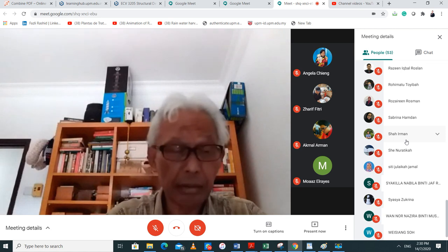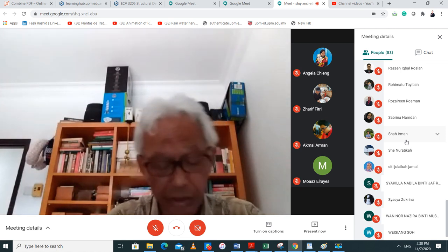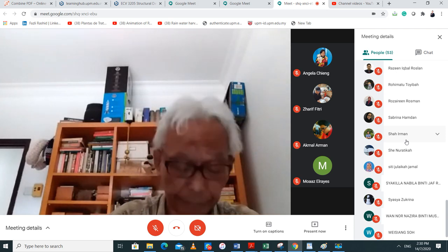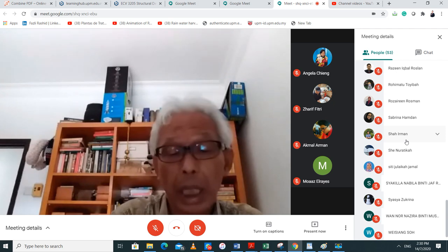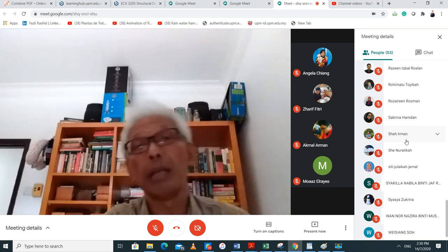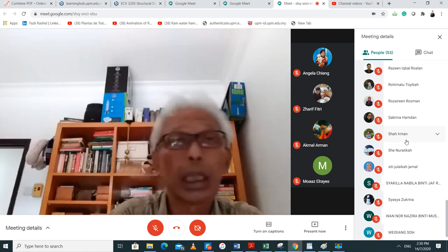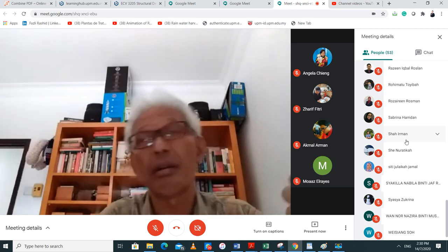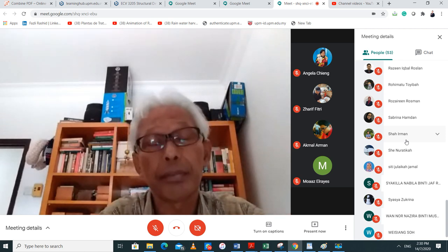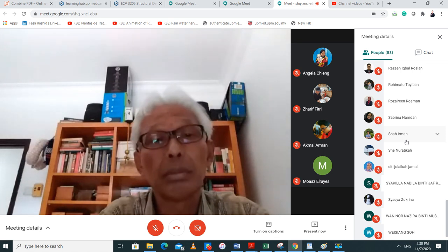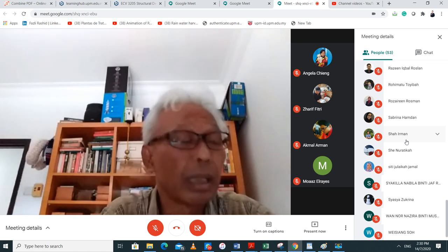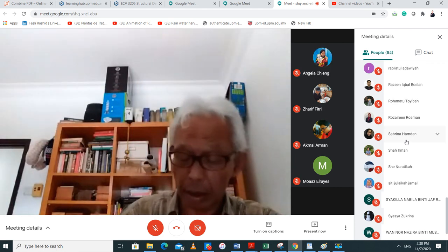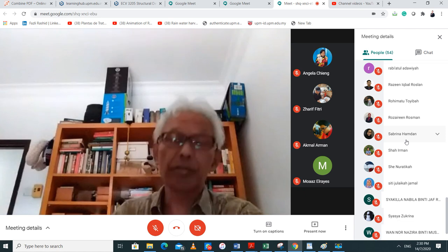And then here, the shaft friction for the pile is equal to the shaft friction of the cone or the SPT. So all this empirical correlation relates the shaft friction and the tip resistance from the result of the SPT and from the result of the CPT. Now we just need to see an example to see how it is being applied. The first example here is example 8.8 on page 308.